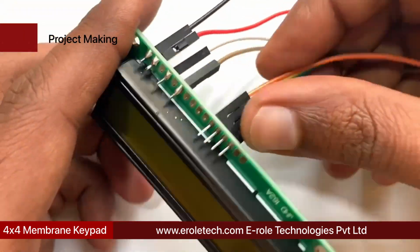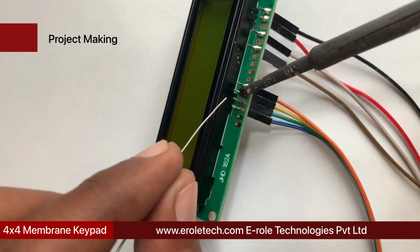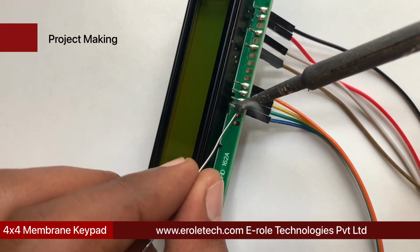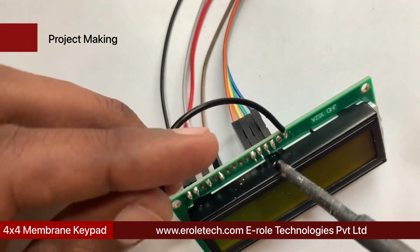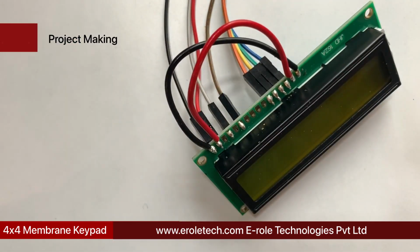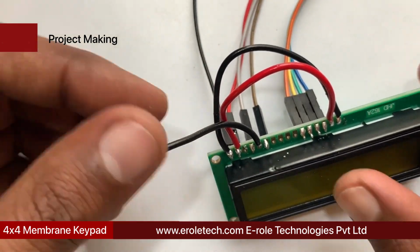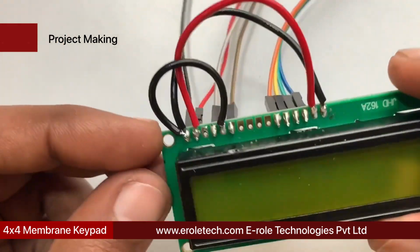Now we will solder orange, yellow, green, and blue wires at pin numbers 11, 12, 13, and 14 of the LCD display. Now connect hole number 16 with hole number 1 using a black wire, and hole number 15 with hole number 2 of the LCD display using a red wire.